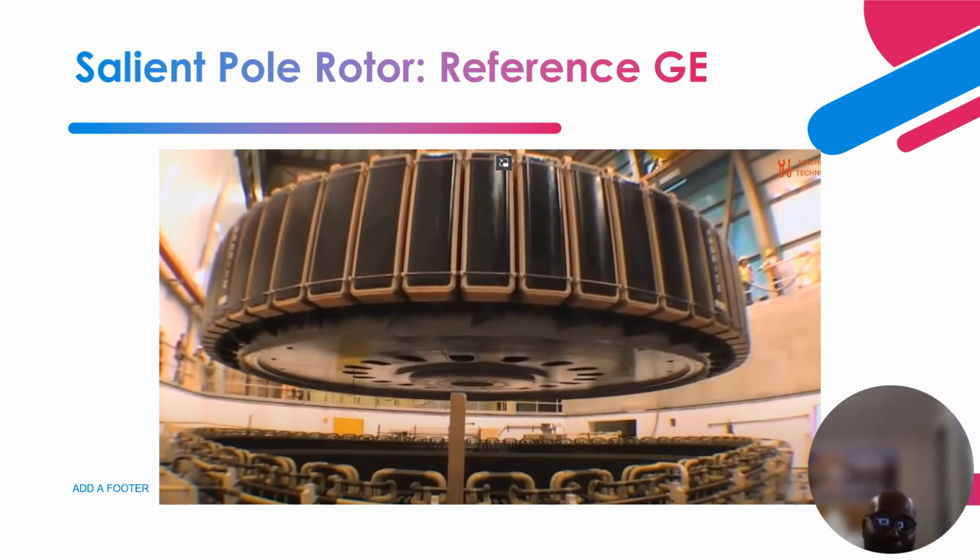Okay, so this is the rotor, right? And these are the poles mounted. Remember, I showed you a picture of the poles, and so this is a typical rotor of the generator. These are the poles, so this is what creates your magnetic field, right? These windings are fed with DC current from the excitation system. Once the excitation system feeds it with DC current, it builds a revolving magnetic field, right?